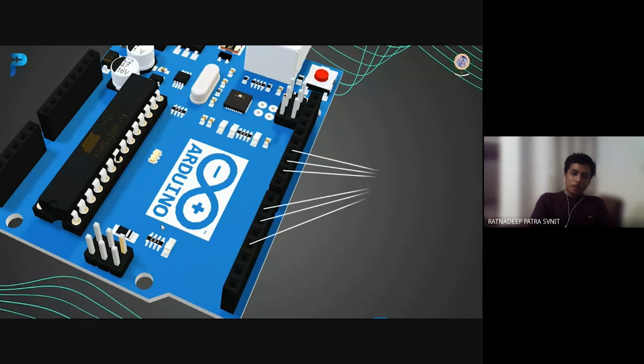Apart from being digital pins, the following pins can also be used for outputting a PWM signal. We saw earlier that the PWM signal is responsible for controlling the RPM of a BLDC motor. Using these pins, we can directly attach a BLDC motor to the Arduino and control its speed.